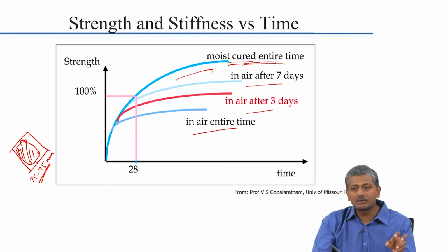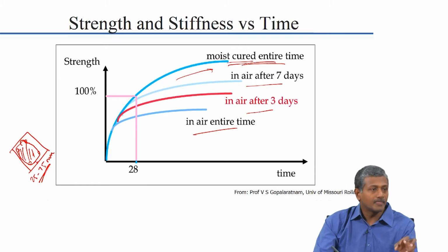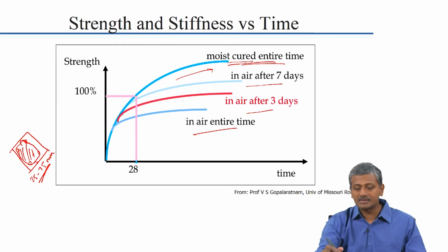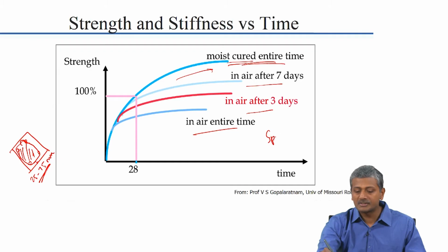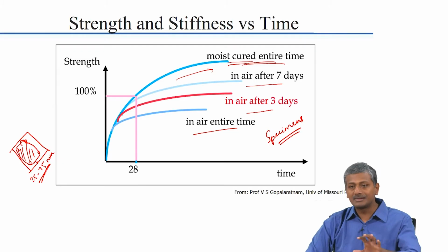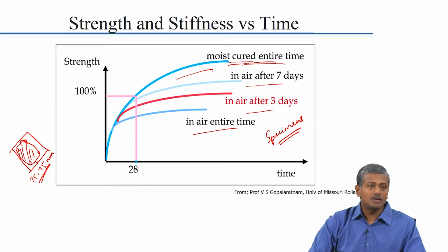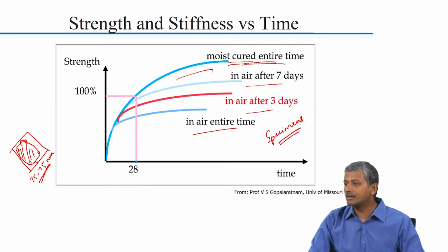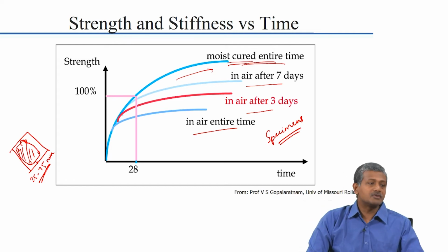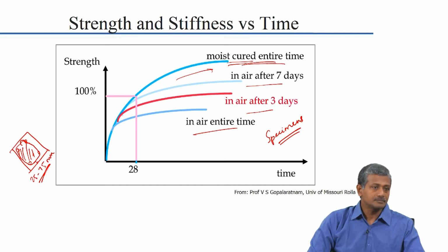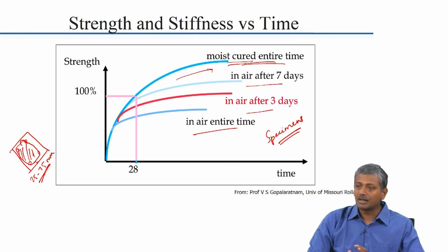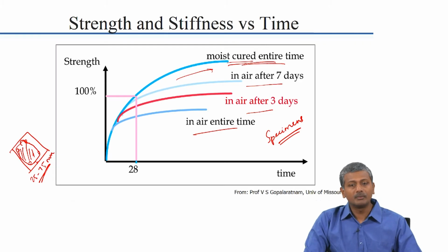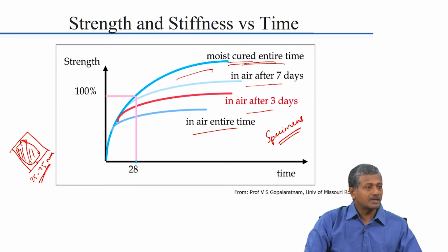But the cover concrete is not really responsible for strength, it is responsible for the durability of the concrete, right. The strength, which is governed by the core concrete, may not truly get affected. So, these are results for cubes or specimens of concrete, but the real structure itself may not reflect this kind of behavior. If you really go to the interior of the structure, you will still get concrete that is properly cured and which has developed its potential strength. Okay. So, again you need to understand how the perspective changes when you move from specimens to the actual concrete on the site.